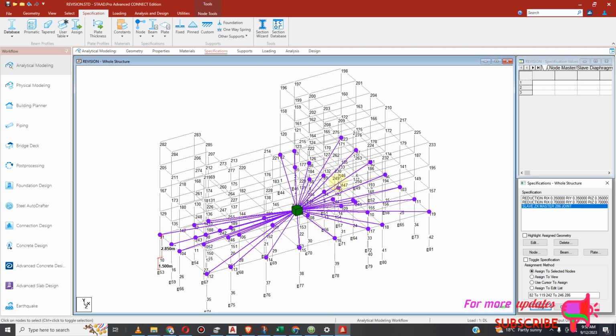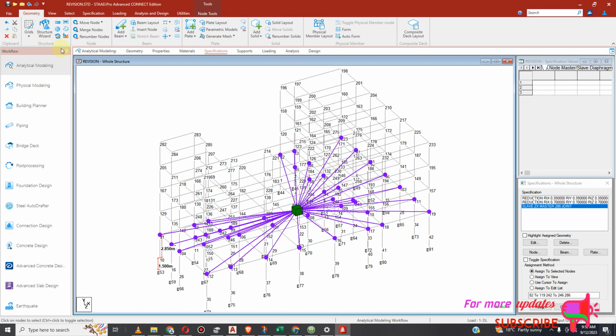especially if you will not model the plates, but you have preferred to add the floor nodes, the floor loads. So if that's how you model your slab in this model, then you have a bit of modeling issues if you don't know the principle of master slave. So this is how you solve your modeling issue. So you assign to the other floors.